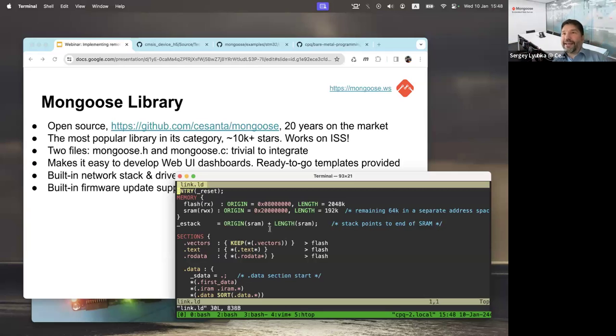If you have an external flash, I'm not sure that the controller can be configured to take on the external flash and map that to the system memory. At least I haven't heard, and I don't know about this. But to my understanding, the answer is no. If the dual bank is supported, it should be supported by the flash controller that goes with the MCU. So with any sort of external flashes, it's not possible. Right. So I hope I answered that question.